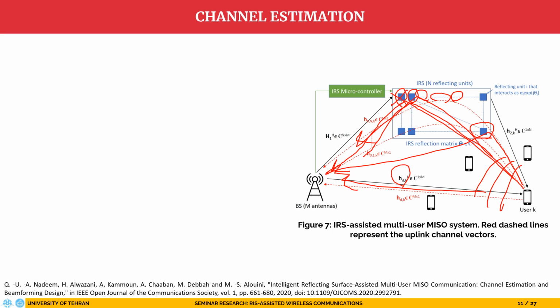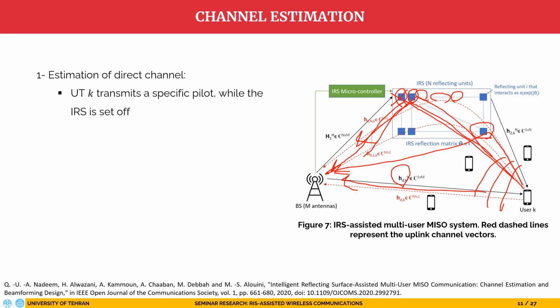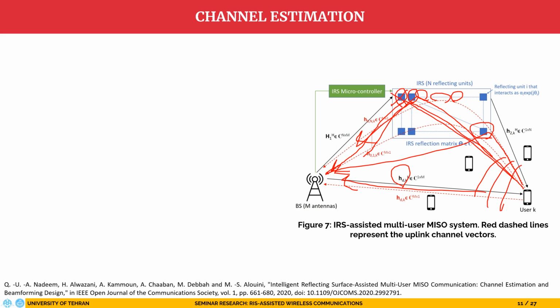So we have all channels corresponding to each element calculated. This is the on-off method, and it is the most basic technique. But it takes some proportion of the channel coherence time, so we would not have that much time to send the intended signals.